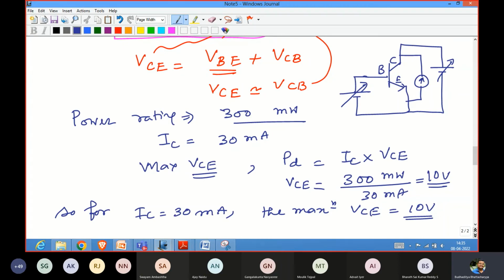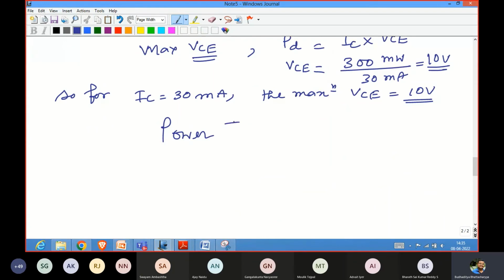That is basically what the power rating of a transistor is. If you require an application where power dissipation can be more, then instead of a normal transistor, we use something called a power transistor. Power transistor is commonly used in analog circuits. This is not in your syllabus, but in a power transistor the base region is actually pretty big, and the collector is even bigger. It has a heat sink added to it, so that the heat dissipated can be completely taken care of. So that is how the power transistor works, and these are the parameters for it.